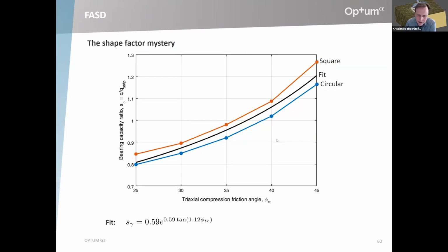Drained analysis of clays, yes, I think it's the same kind of thing. I think you have exactly the same effect for the drained friction angle of clays. There's a lot less data out there, but the data I've seen tend to suggest that there is this effect as well. I showed you some before, but there are others as well. So I would say yes, there is probably the same effect for clays as well.